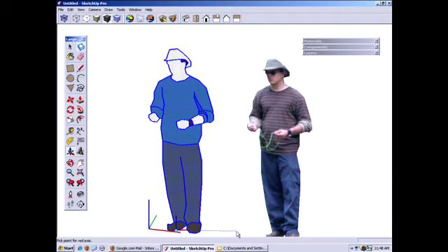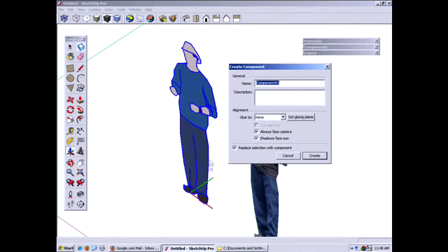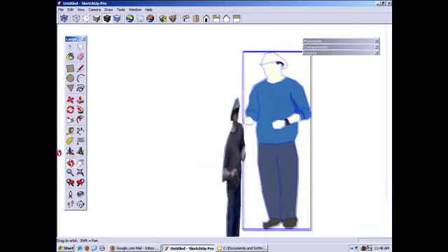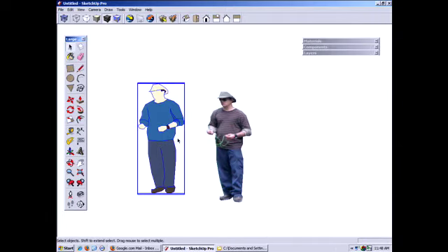Click once, pull away, set the red axis, and then I'm setting the green axis now. You do want to be careful. You see how if I pull forward, that blue axis is down. It causes some problems, so I'd want to make sure green is back, blue is up, and create that. Okay, now it's going to behave more correctly.